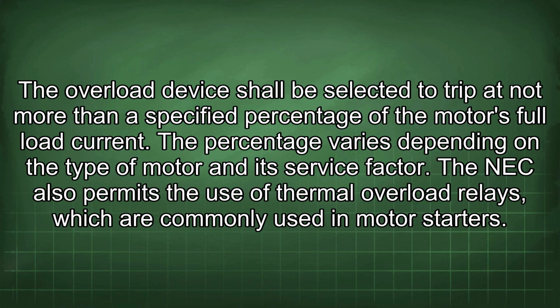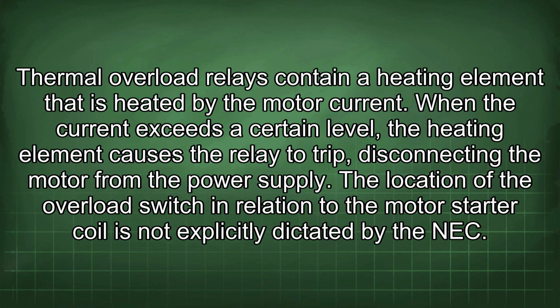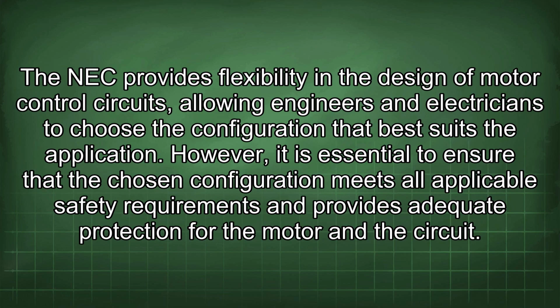The NEC also permits the use of thermal overload relays, which are commonly used in motor starters. Thermal overload relays contain a heating element that is heated by the motor current. When the current exceeds a certain level, the heating element causes the relay to trip, disconnecting the motor from the power supply. The location of the overload switch in relation to the motor starter coil is not explicitly dictated by the NEC. The NEC provides flexibility in the design of motor control circuits, allowing engineers and electricians to choose the configuration that best suits the application.